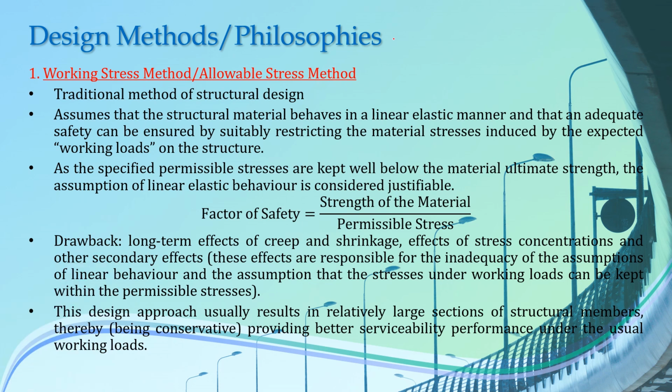So that means there are always two sides to an equation that is concerned with the design of our structure. Let's say that the left hand side is the demand side and the right hand side is the capacity side. Demand means the load effects, or the effects that the loads create on our structure, the internal forces that various loads generate on our structure, or the magnitude of load that should be resisted by our structure. That is known as the demand imposed on our structure.